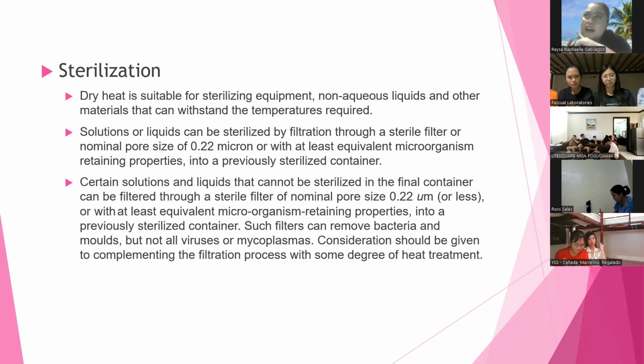But products that cannot withstand high temperatures, most of them are just filtered. Of course, we have GMP for the filtration process. The pore size is at least 0.22 micron. This is the size of filter that can really filter out microorganisms.